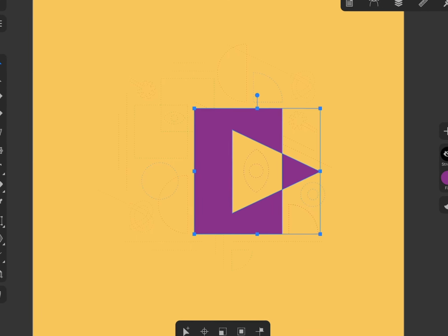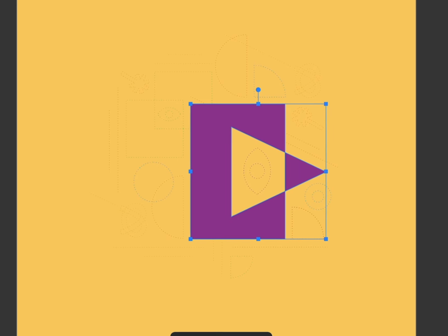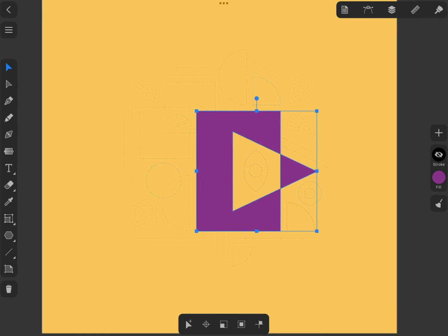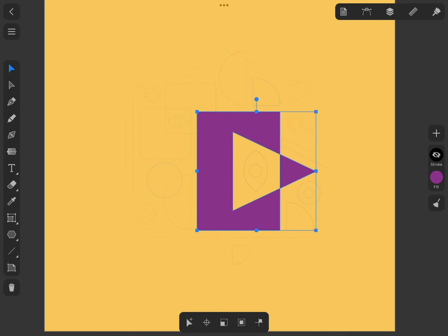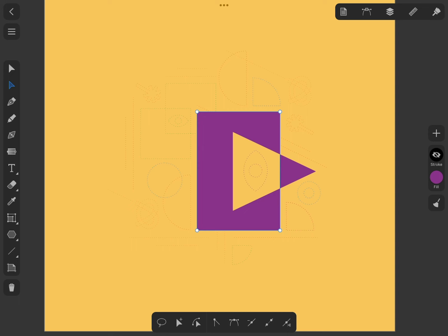Despite the newly created shape, it behaves as a single object. You can still edit it by moving the triangle or the rectangle. For this, deselect the entire shape. Switch to the Selection tool and drag either the rectangle or the triangle to see the shape change on the fly. Since you can still modify the resulting shape after applying Boolean operations, they are called non-destructive operations.